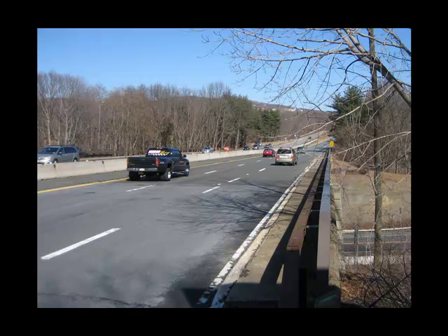And on the other side of this concrete barrier, there are 2 southbound lanes as well as an acceleration lane from an entrance ramp. So there's a great deal of width, and it is very feasible to divide this bridge in half, shift all the traffic onto one side while you demolish and replace the other side. That's the classic approach. When you have that kind of room, you have a very straightforward project.